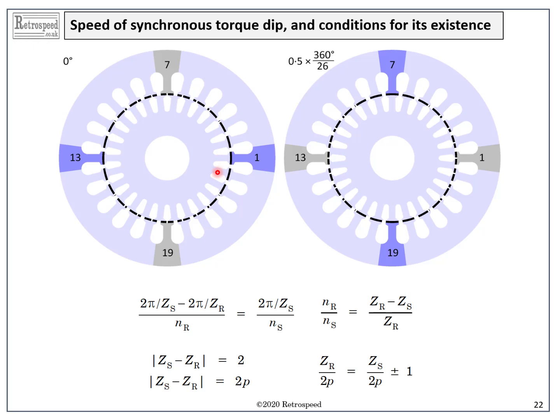Going round the air gap, we can see a two-pole pattern of alignments, really a stepped gradation of alignments, but with a definite two-pole structure. This is what causes the trouble, and it arises naturally with a difference of 2 in the slot numbers, as expressed by this equation at lower left.